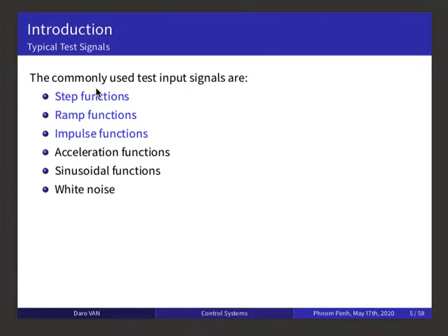On the other hand, if the system is subjected to a shock input, an impulse function may be the best. When the control system is designed on the basis of test signals, the performance of the system in response to actual inputs is generally satisfactory.